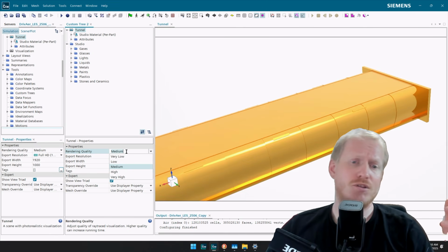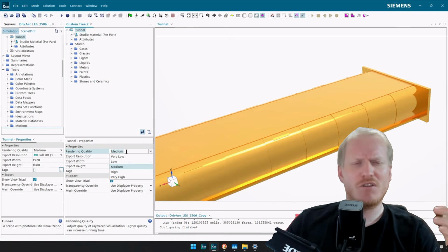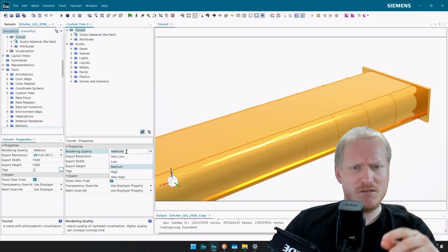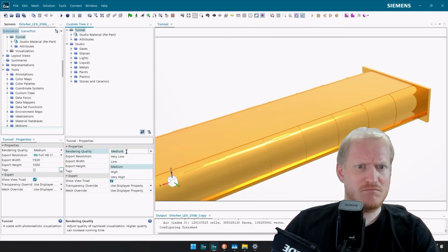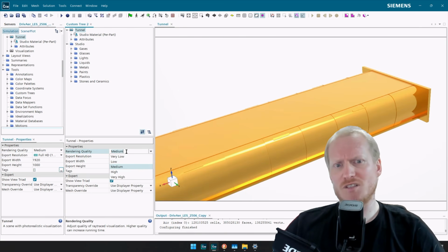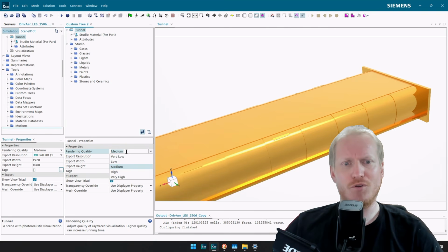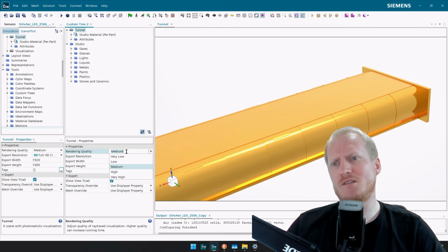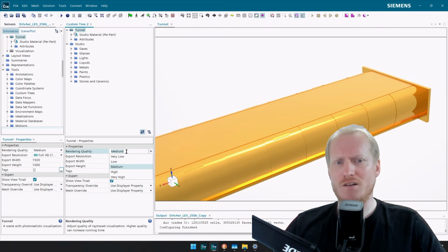Before, you fine-tuned numerical values for quality, a number from 0 to 1 on a logarithmic scale, so 1 literally rendered forever, and 0.5, 0.6 was your normal setting, plus minimum and maximum render passes per pixel, and denoising and such.